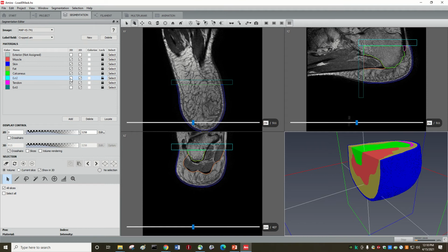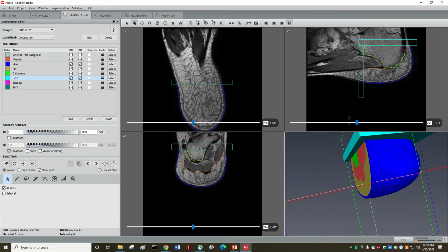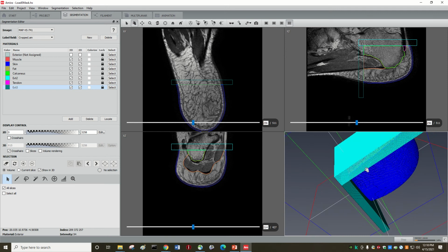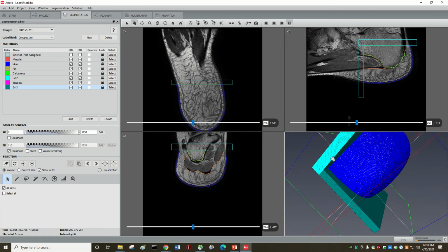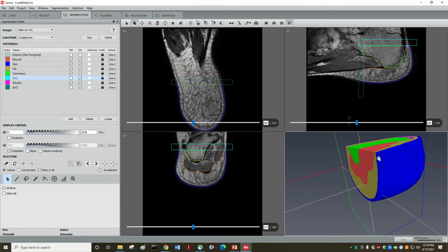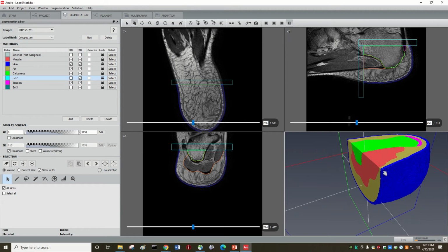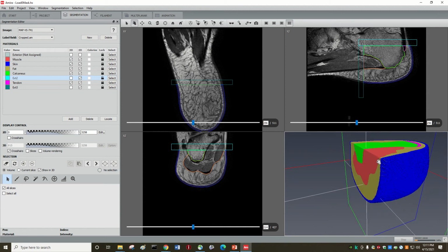And what can be useful to do is to add some materials that sort of cover the cut, okay? So in this case, I'm using two of them. And this is because if we don't add these two blocks, all the smooth things will smooth out, for example, this line and this corner. This will create these regions to be harder to mesh in the next steps.